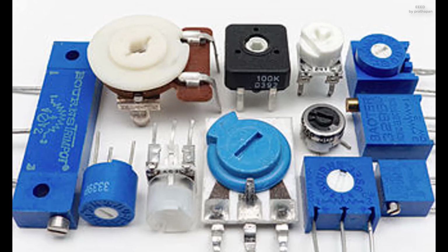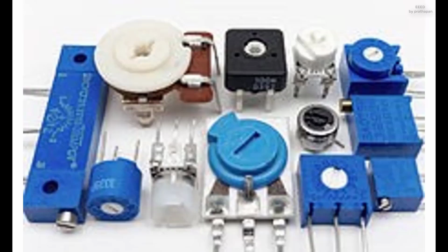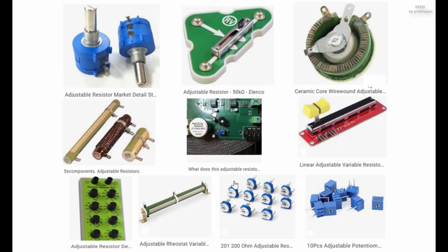A typical low-power potentiometer, see drawing, is constructed of a flat resistance element, B, of carbon composition, metal film, or conductive plastic, with a springy phosphor bronze wiper contact, C, which moves along the surface. An alternate construction is resistance wire wound on a form, with the wiper sliding axially along the coil. These have lower resolution, since as the wiper moves the resistance changes in steps equal to the resistance of a single turn. High-resolution multi-turn potentiometers are used in precision applications.